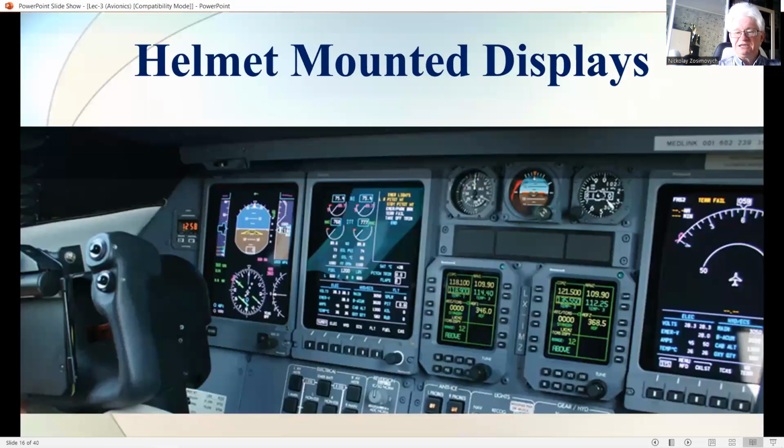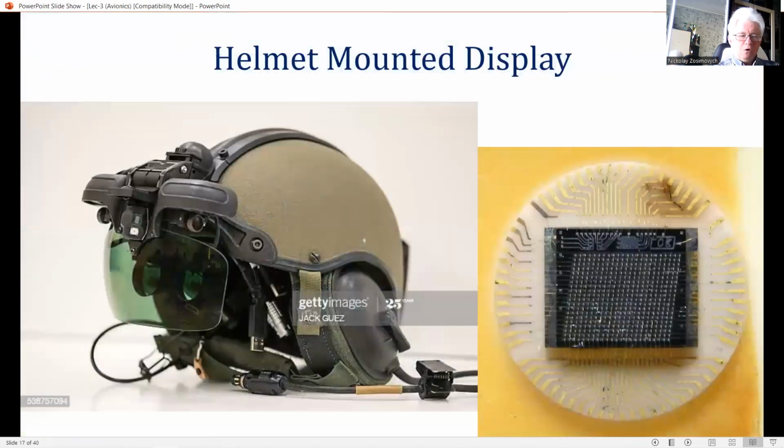Another subtopic in today's lecture is the helmet-mounted display. As mentioned in the introduction, the HMD can function as a HUD on the helmet and provide the display for an integrated night vision viewing system, with flight and weapon aiming symbology overlying the projected image from the sensor. Also, monocular HMDs have been built which are capable of displaying all the information normally displayed on a HUD.